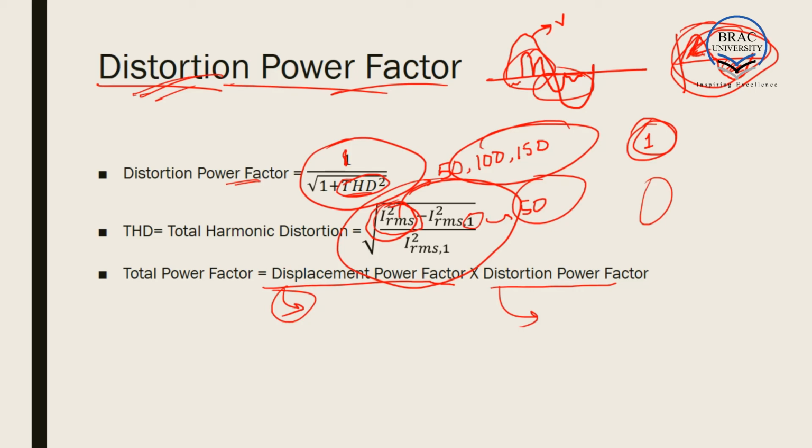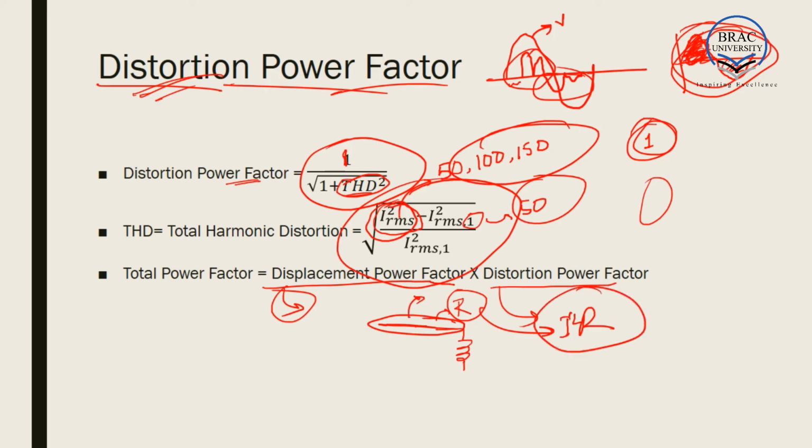Then why is the power factor important? Power factor is important because when an inductor is connected in a circuit, there are wires which are meant to have 0 resistance, or to be perfectly conductive. But in the real world, the wires are not perfectly conductive and there is resistance. And this positive current, when passed through resistance, gives I square R. This I square R is our loss factor, and it is completely lost.